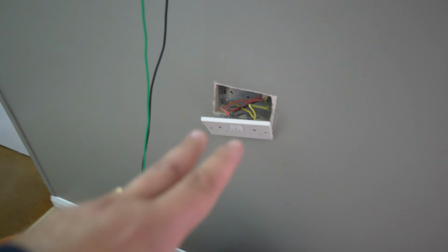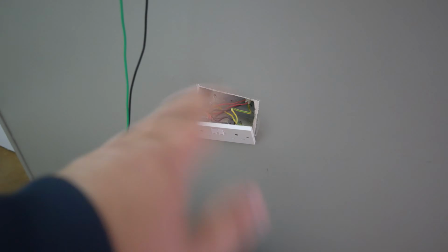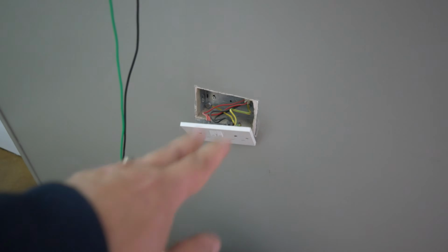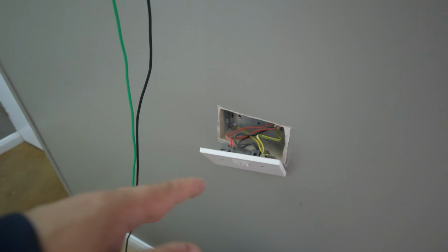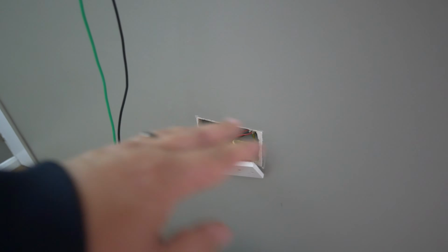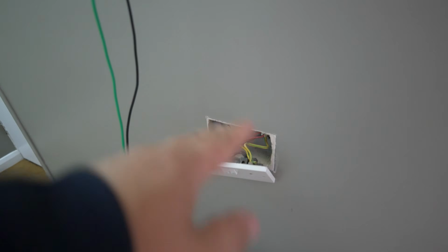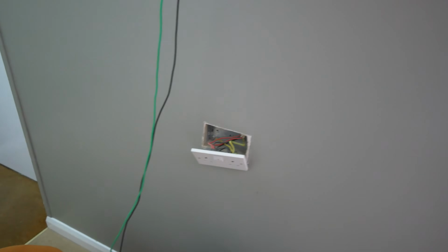So say for example, you've done your R1, R2 around all the socket circuits, and one in particular was presenting a higher value. You could open it up because you'd need to see if there was a problem with the terminations anyway, and see if they were okay, take a measurement, and then you know with pretty high confidence that the issue is with the accessory itself.